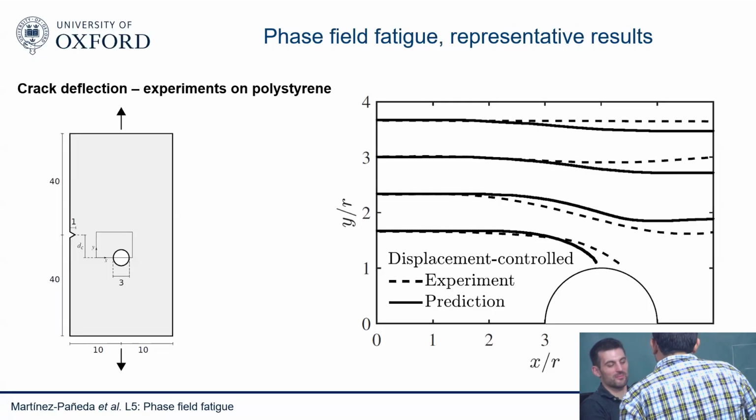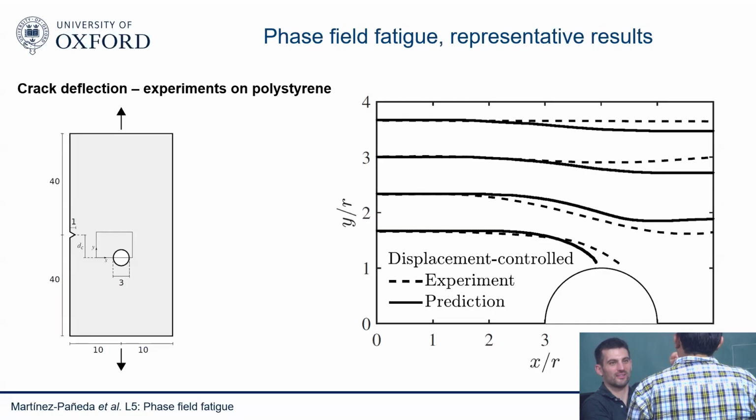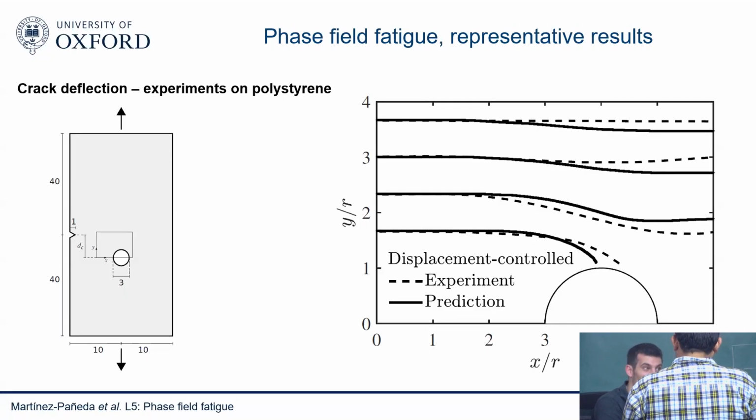Is it fully symmetric, or are you holding it at the bottom? It's a 4-point bending test. So it should go straight, ideally. I think the crack will see the hole, depending on the distance of the hole. But the question is, why would it see one hole and not the other, particularly when it's 4-point bending, which is fully symmetric? Interesting. I guess that could be microstructure or something. But if you do many experiments and they always follow the same hole, that's.